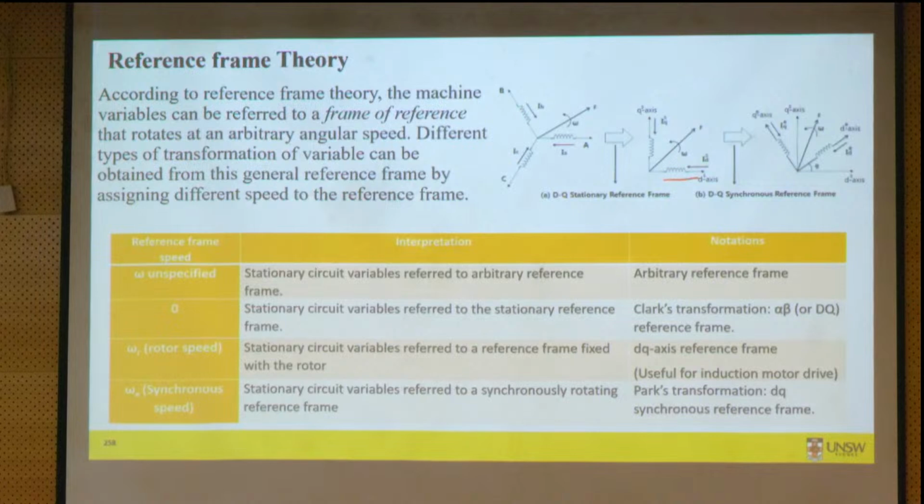We can imagine we have two windings, one in the D-axis and the other in the Q-axis, and if we pass ID current and IQ current to these two windings, they will produce the same rotating magnetic field, or same space vector. Remember we discussed the space vector, which combines Va, Vb, Vc together to give you that rotating resultant voltage, or resultant flux, or the resultant rotating magnetic field.